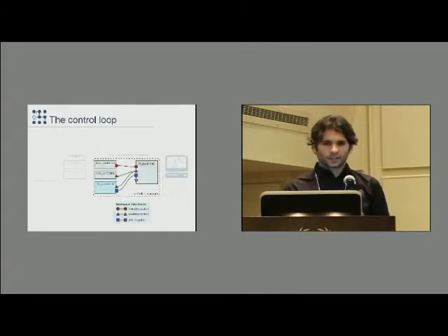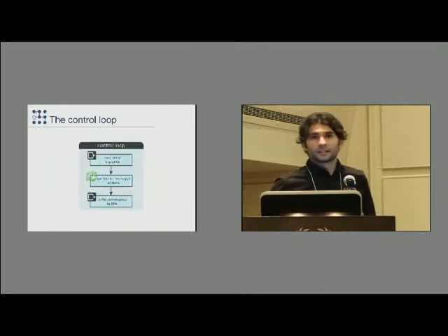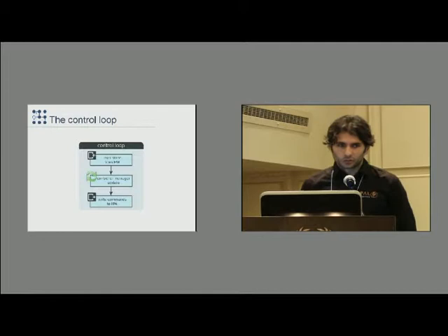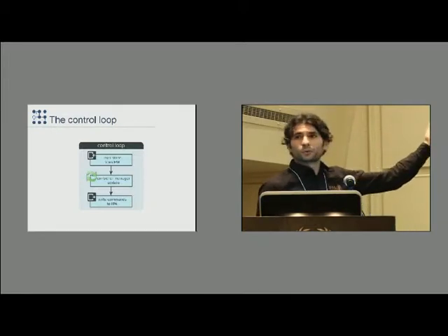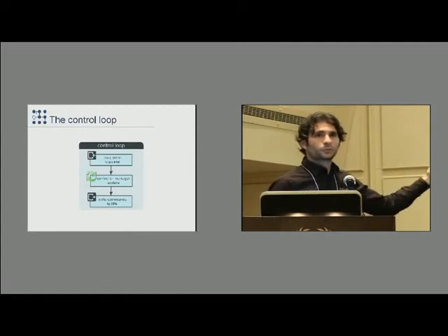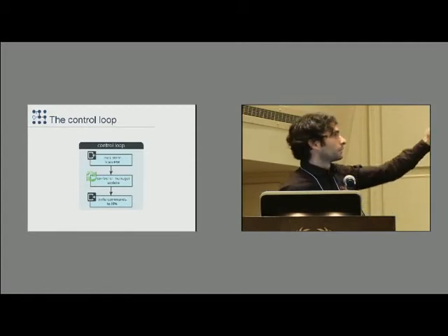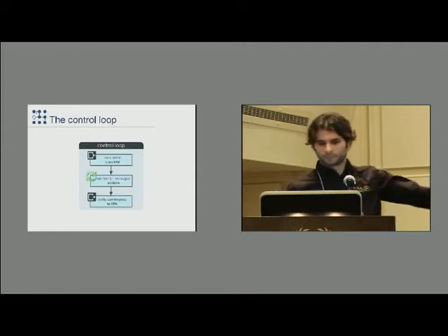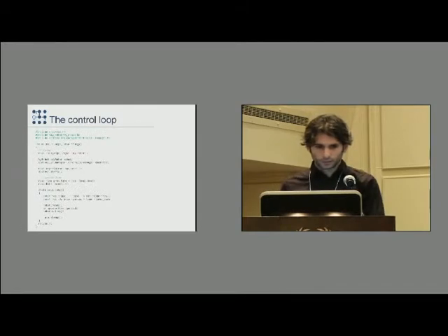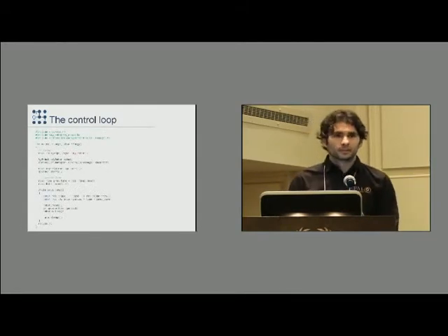But so far we haven't actually mentioned the actual control loop, so here it is in its most basic form. Typically what you want to do is read the state from hardware, update your controllers with the current state, which in our case is done by the controller manager, and then finally the commands that come out of the update, you send out to hardware.